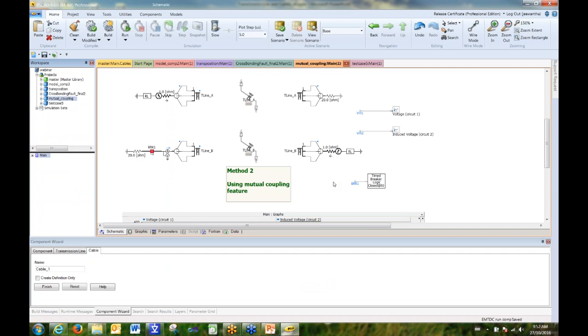The next question is, what happens if you get negative RLC values? All you have to do is forget about the long line corrected values. Calculate the total RLC values as the RLC values per unit length times the total length of the transmission line.